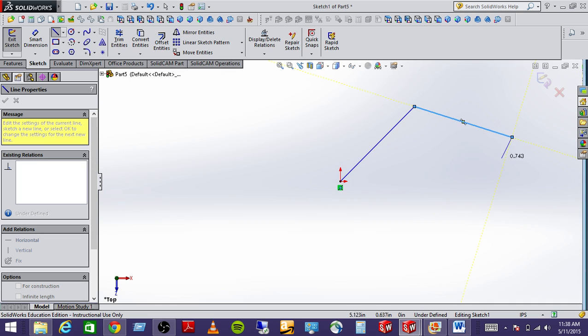Now look what's happening. SolidWorks does what's called snap. It'll do some snaps and you can set that in your options. As I'm dragging around, it is trying to figure out what I want. It's trying to guess for me. See this little dotted line it just put in, that vertical dotted line? What would you imagine it's trying to guess there? It's a good try, but what do you think that specific vertical dotted line is guessing that I want? Not quite. It's guessing that I want those 2 points to be vertically oriented with respect to each other.